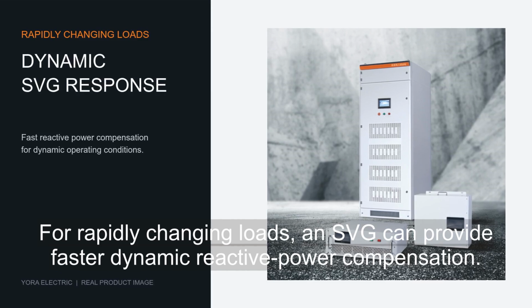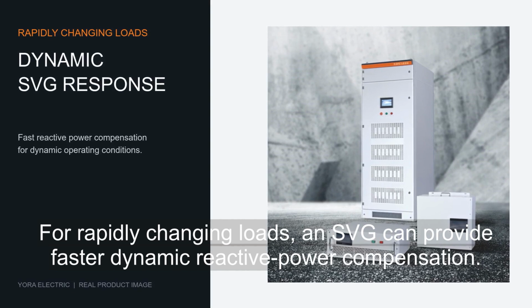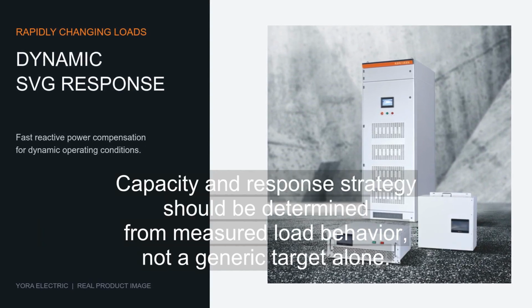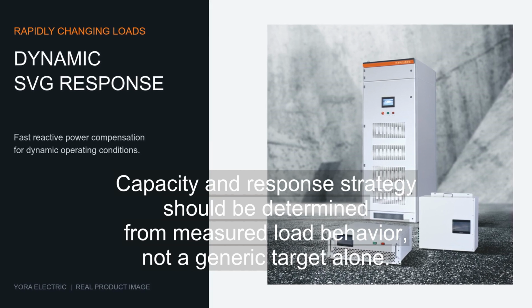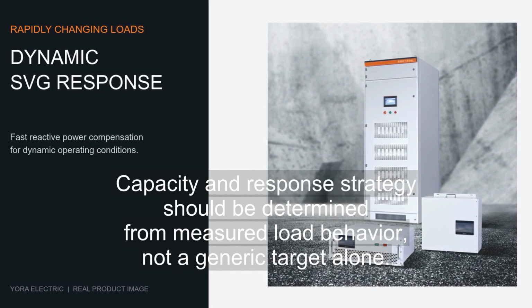When loads change rapidly, a static VAR generator, or SVG, can provide faster dynamic reactive power compensation. The required capacity and response strategy should be determined from measured load behavior, not from a generic target alone.